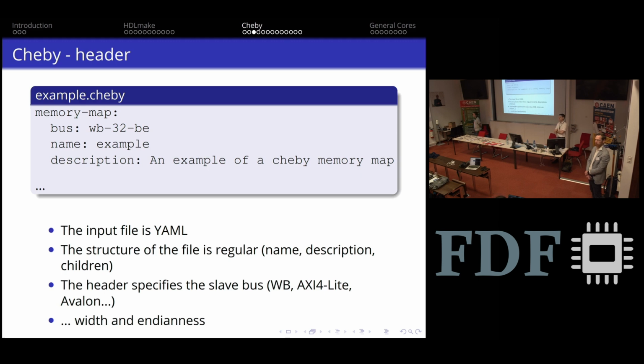How do you handle this type of challenge? We use a transceiver from the vendor, and then we have, I would say, a little bit of adaptation layer. Then we have a common interface inside White Rabbit. To talk about it a bit more, most of the Xilinx transceivers don't provide any indication of how they slide bits into words, so you don't know what delay is added by the transceiver.